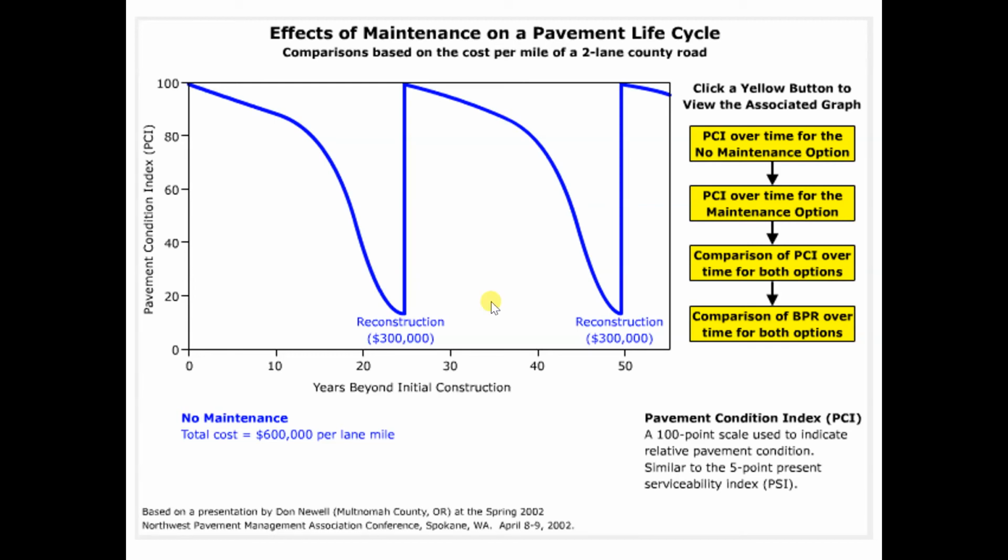So the same thing goes with the pavement. If you don't do any servicing, you just don't care, don't patch the potholes, don't seal the cracks, the pavement will just totally become unserviceable. It's in such a bad state that you cannot do any maintenance to bring it back, so in that case you need to do the reconstruction.